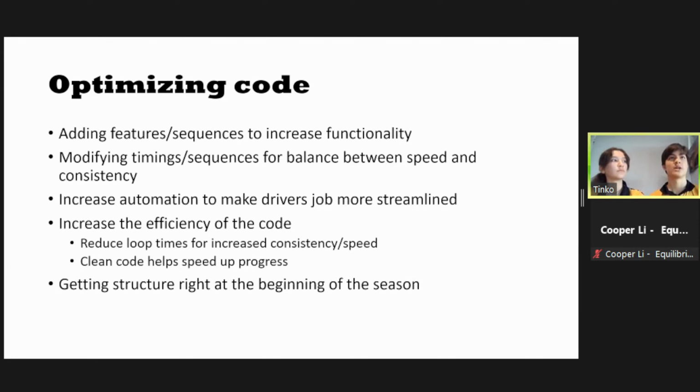Yeah, so we actually had a lot of issues with loop times coming up to Worlds last season, a lot of it was silly mistakes. For example, double reading or double writing specific hardware devices, not putting all of our sensors onto the same platform. We forgot to stop streaming after Autonomous finished, so we were still streaming. That was obviously not good. But once you clean out all those things, your control loops should be better, which helps with consistency as well.